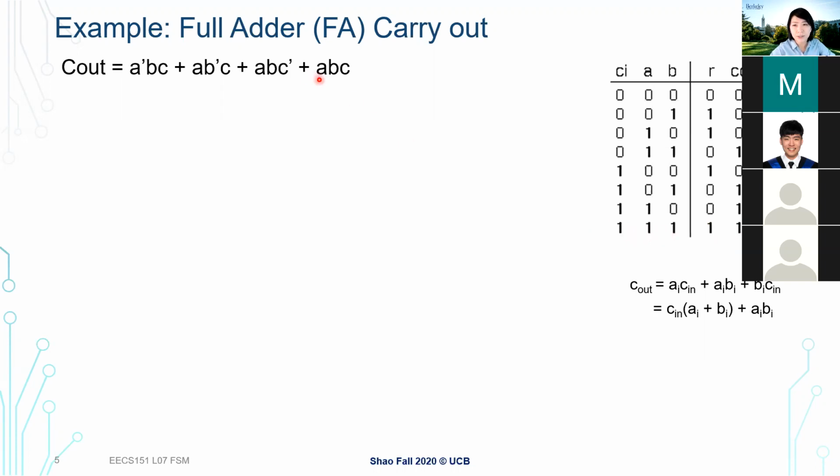We also mentioned earlier that we wrote the carry out directly. It's basically two levels with an OR gate here. Sometimes you also see people call this a majority gate. Basically, it looks at the majority of the signals: if the majority of signals are 1, the output is 1. If the majority of signals are 0, the output is 0. So this is also a good example of the majority gate.